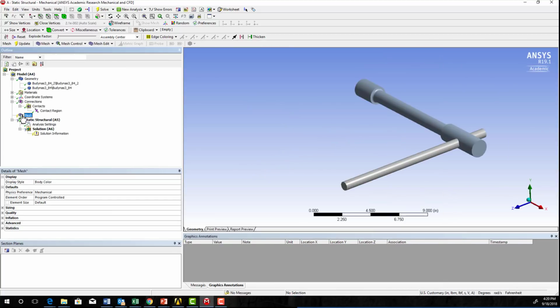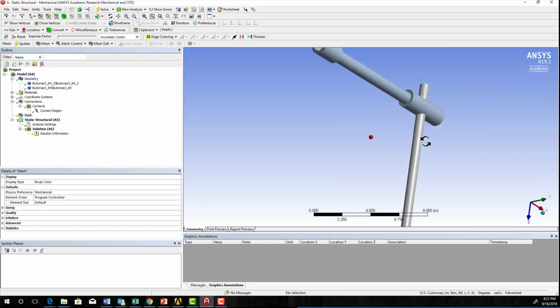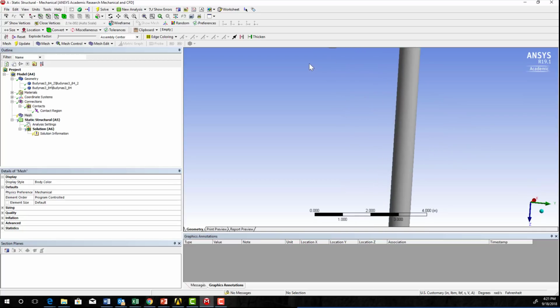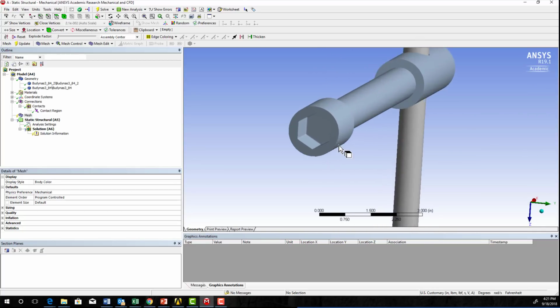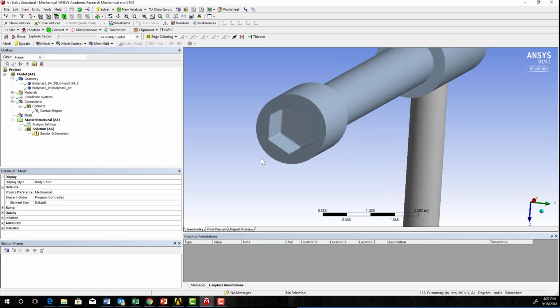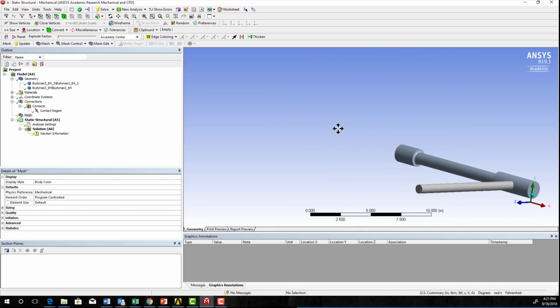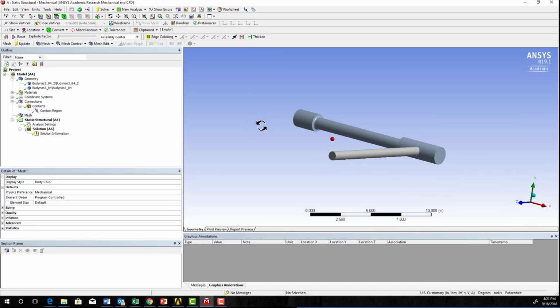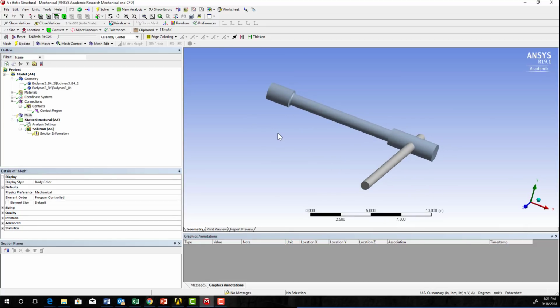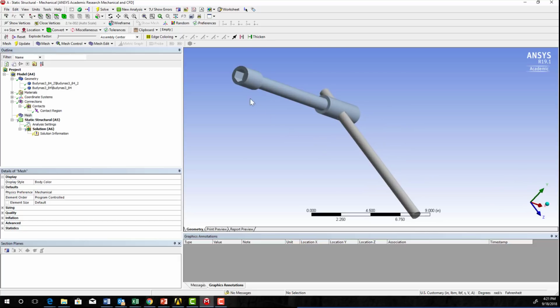Mesh, you've seen some basics of meshing here. Again, you can apply principles of refinement. You may want to pay close attention to how many elements you have in the contact area. Refining there could be profitable. Note that these features, and particularly the fine fillet radii in here, could pose a challenge. Now, I'm just going to show you the basic idea. I want you to think about how you might do this and do this better. So I'm going to show you a basic solution.